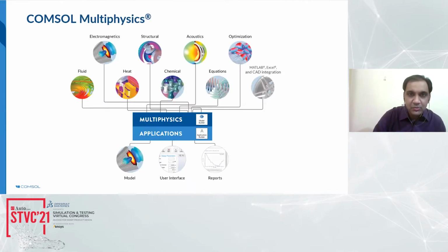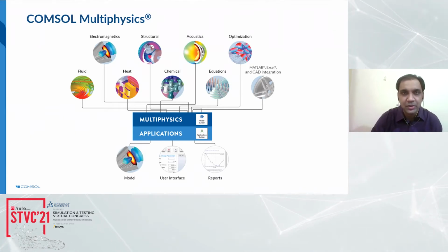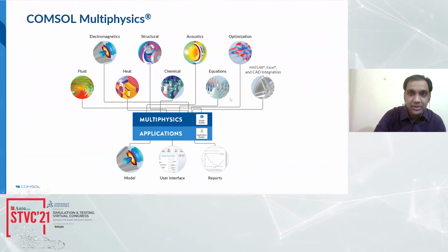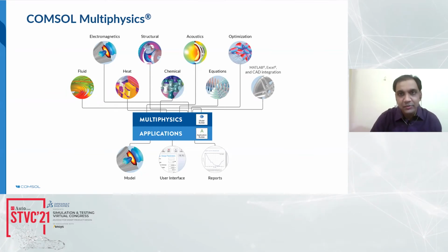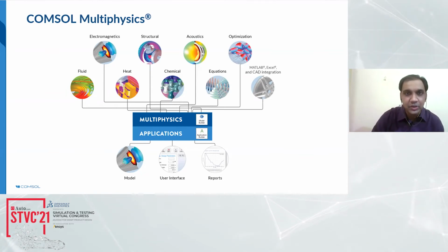So this is how COMSOL looks. It has the Multiphysics platform product, which has various add-on products like electromagnetics, structural, acoustics, optimization, etc. Today our focus is on acoustics and a little bit on the structural part to model all those automotive acoustics applications in COMSOL. More importantly, it also has equation-based modeling where you can write your own equation. And apart from modeling all these physics individually, you can combine all of them and perform a multiphysics simulation. So this is basically the Model Builder part.